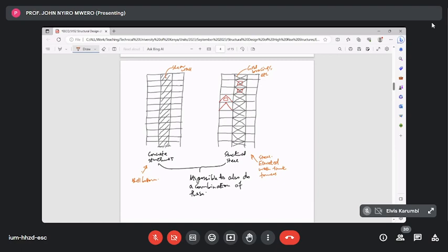We'll discuss tanks in the low-rise building unit. But this structural steel tower is always braced like this, and that bracing is to stiffen it in the lateral direction so that it doesn't sway too much. So those cross bracings are the stiffening element, and the same principle is applied also for buildings. So if you're doing a tall building in structural steel, you do this.